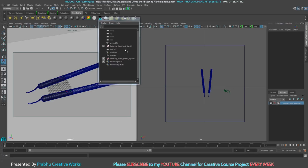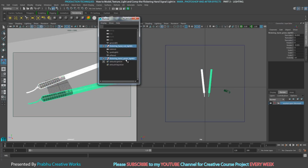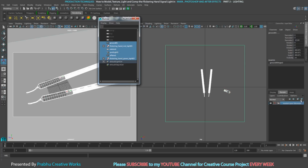In the first layer, you want to select all the objects and then all the lights and all the cameras, and click this last button to make a new layer. So it will automatically add to this layer when you click this button. So you want to select all the objects, click this button and rename this layer as color, CLR.